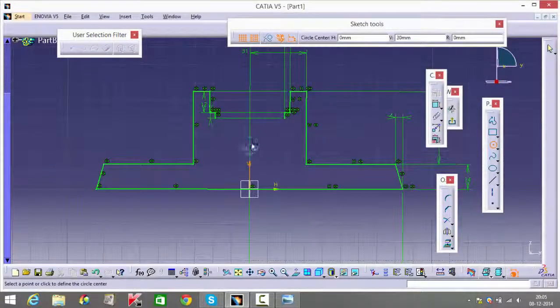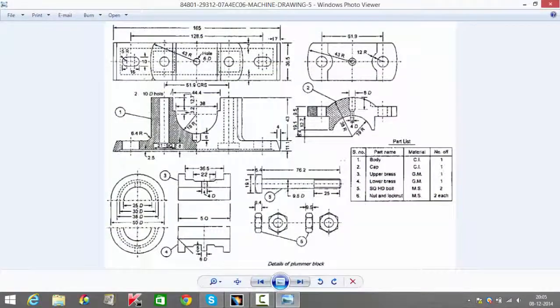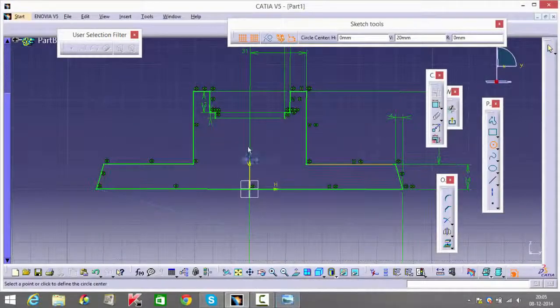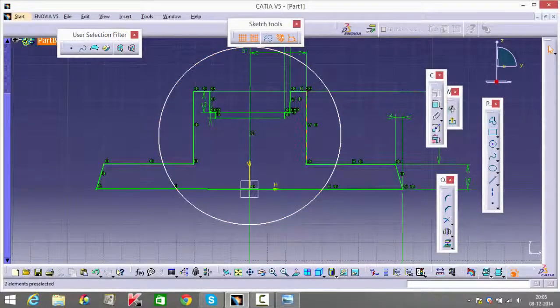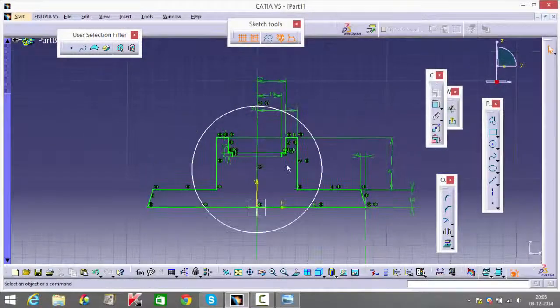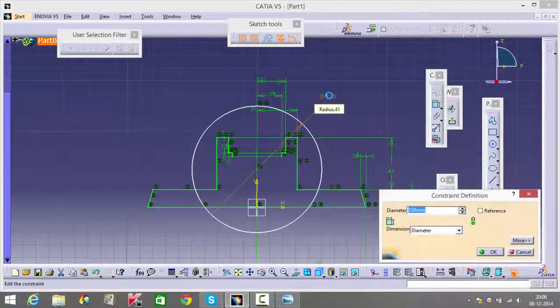What you have left is to finish off this semicircular structure. The reason I drew the 3 is so that it will automatically become tangent with the circle when I erase the other portion of the circle. I'm making the circle big initially because I don't want it to get constrained with any of the inside parts. If that happens, when you're erasing you won't figure out what's wrong, and it's very annoying.